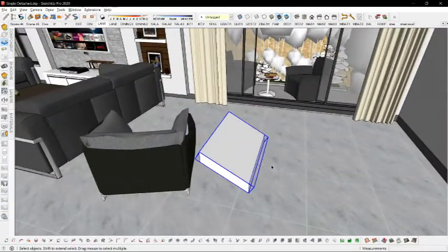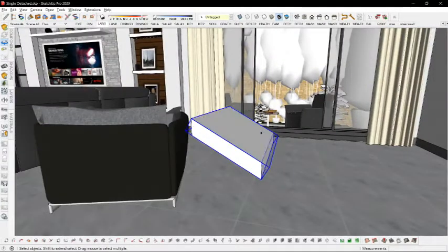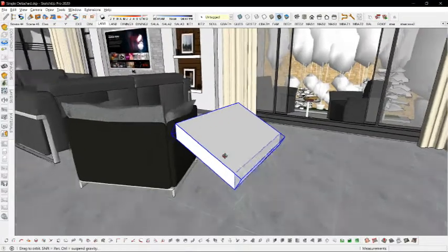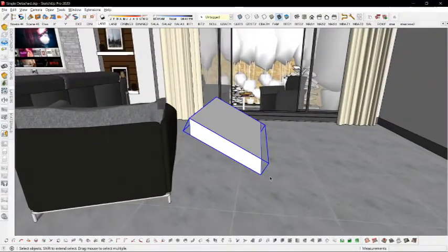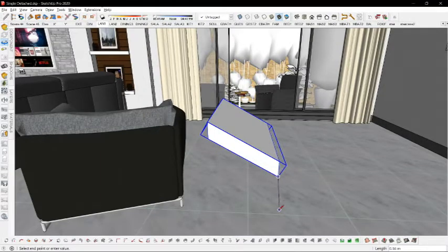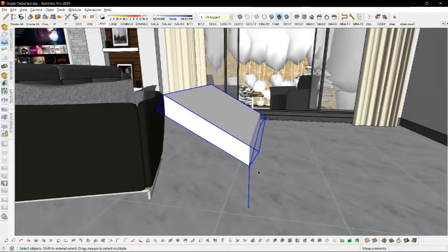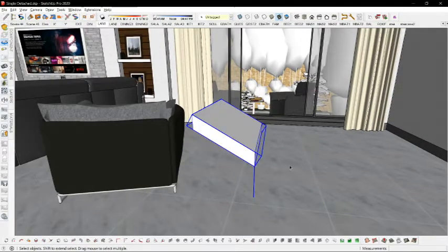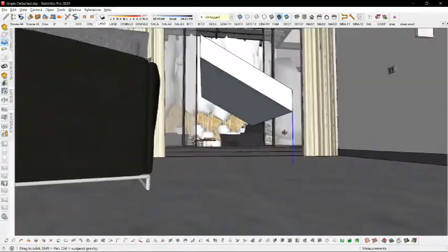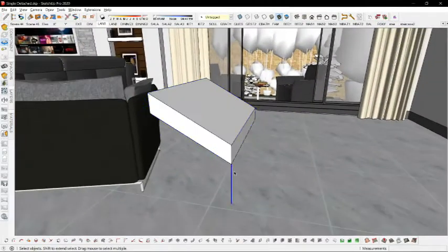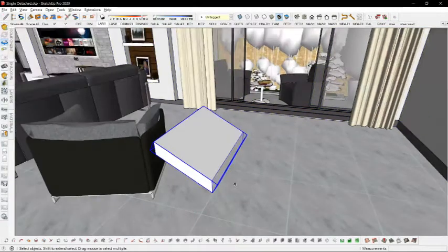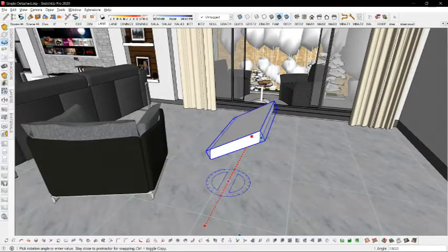However, in cases like this, if I try to flip them along a certain axis, it just goes along its own. In this case, I just draw an extra line, downwards or upwards, select them both, and try to flip them. This time it is following the world or the model's axis, because this drawing's axis is more stringent than the component. It doesn't do anything, so I have to click. Now it locks. This is for mirroring.